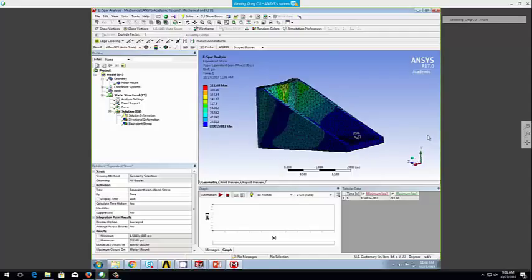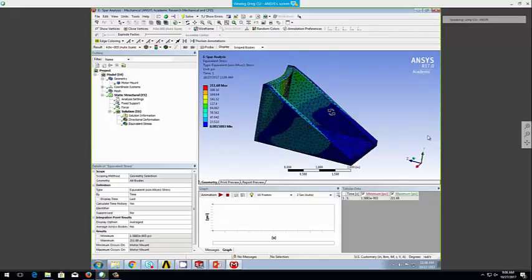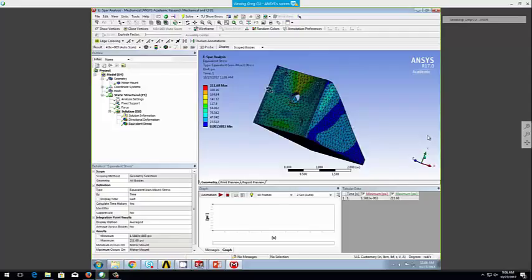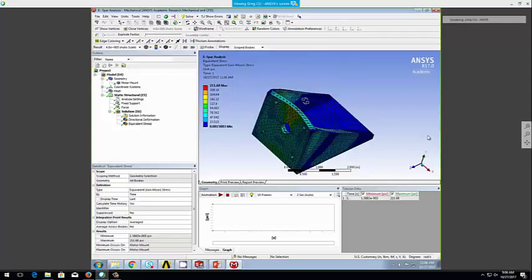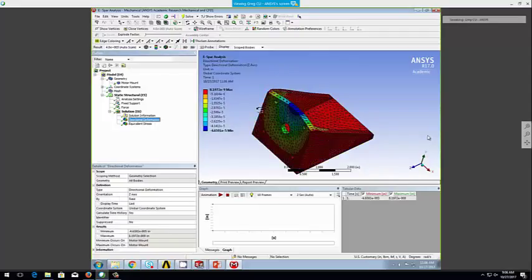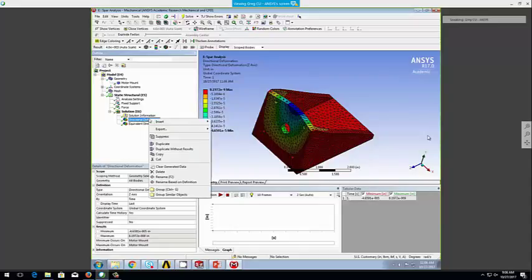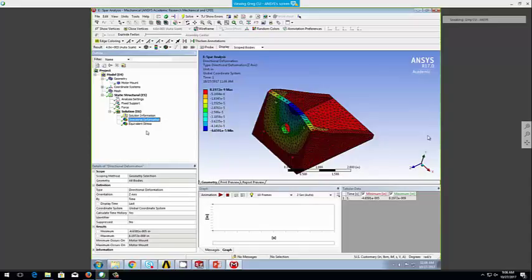Carbon fiber is typically directional, okay? This is the tensile modulus of the carbon fibers themselves, but you mix carbon fibers in with epoxies to make carbon fiber reinforced polymer. You'll see it has a lesser tensile modulus, okay? And so you need to look at these sorts of things so that you know what material properties to put into your simulation.